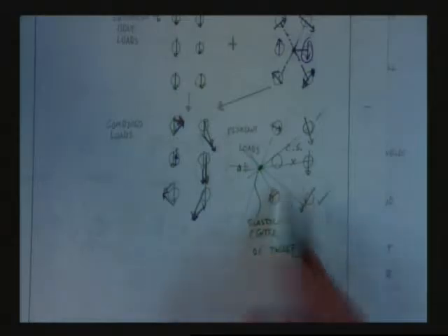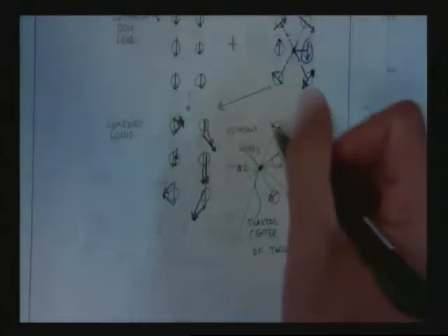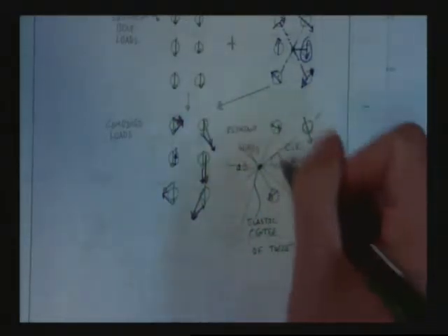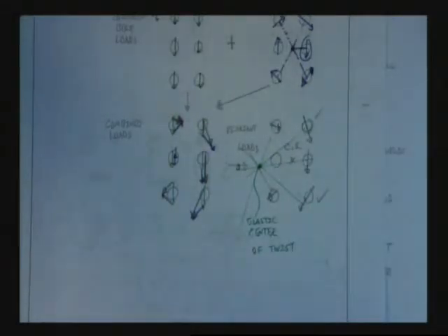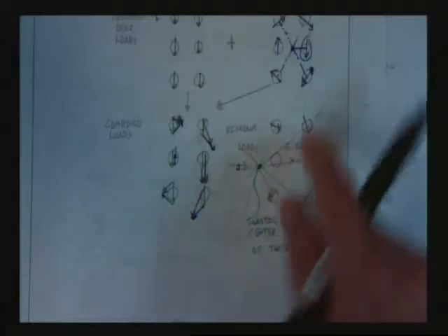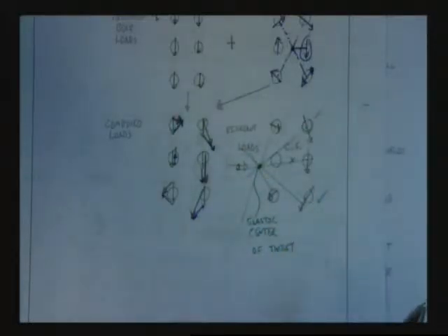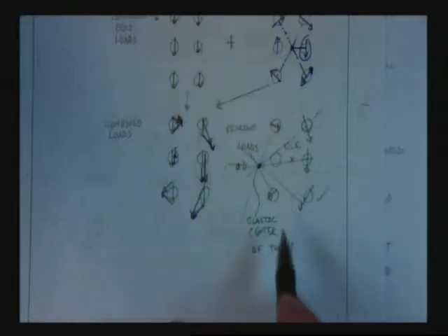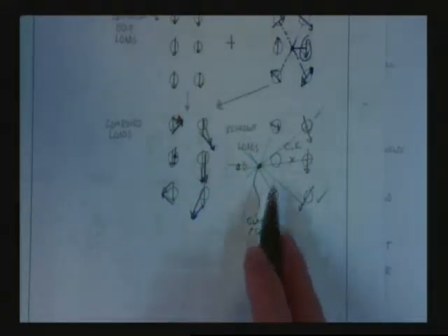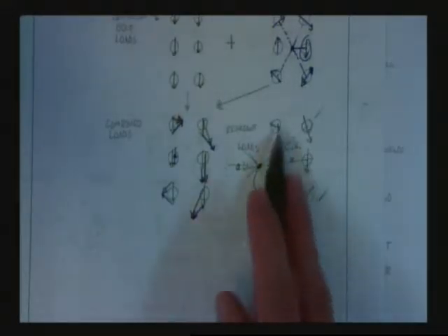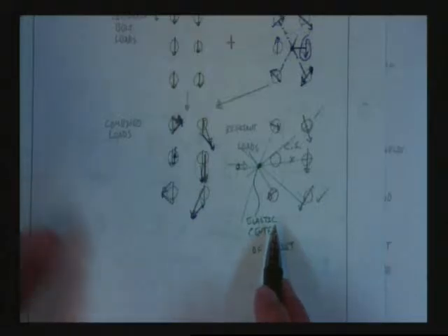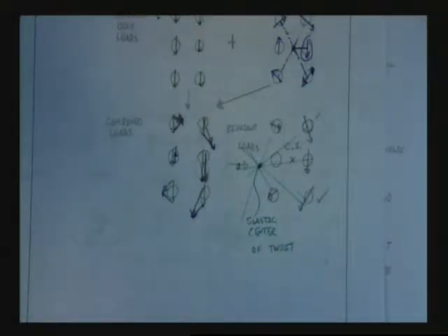And what we're going to find is that eventually every one of these bolts is going to reach its limit state. Every one of them. And that's going to require some localized yielding and localized movement of our plates and our bolts. And we've got some safety factors built into our techniques so that no individual bolt will fracture. And what we'll find out is a really easy, simple solution that provides conservative results. And who doesn't like that? Right? Who doesn't like that?